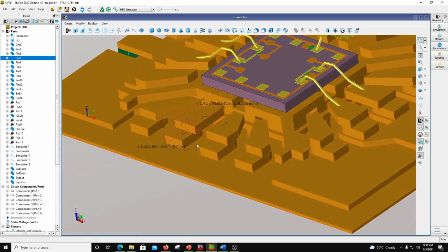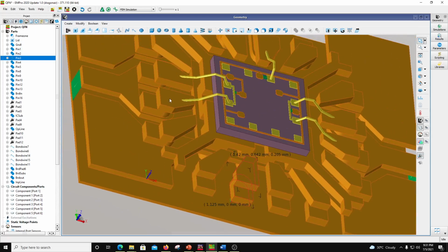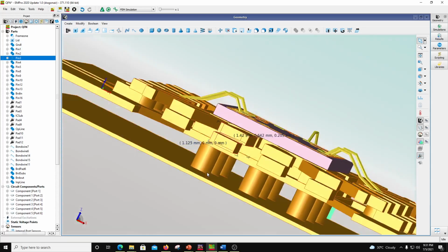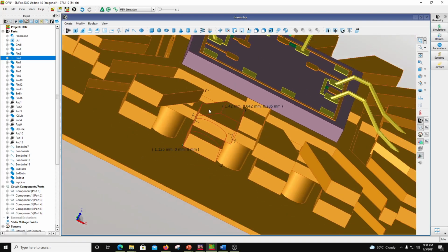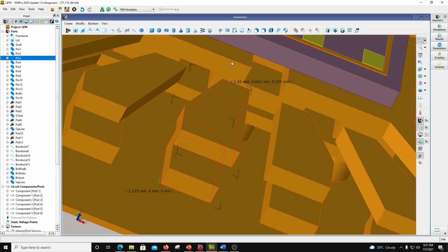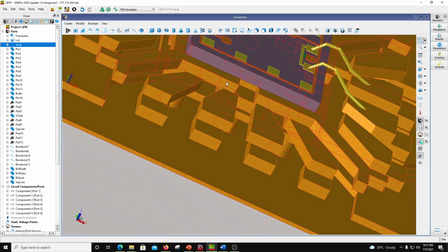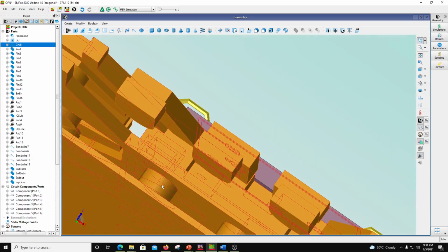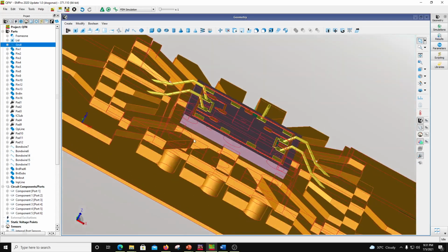And this pin to which the bond wire comes, so all these pins are QFN pins. And then you see that this is the via of the board, but then the QFN has a pedestal, which may be solid. So in this case this pedestal is solid, right? So that ground comes from there, from the central pedestal. Okay, so that's the central pedestal from where the ground comes into this chip, right?